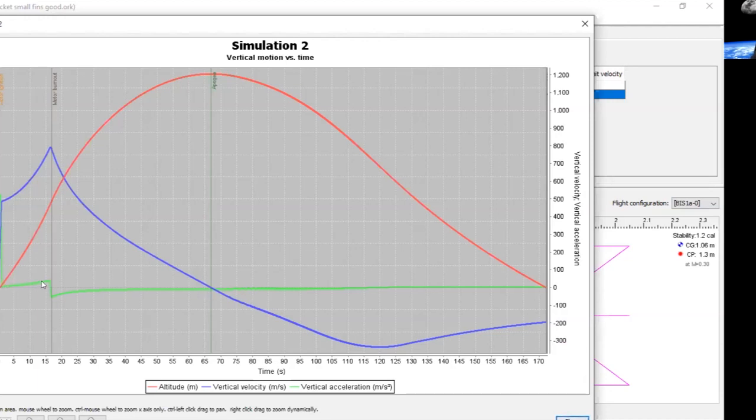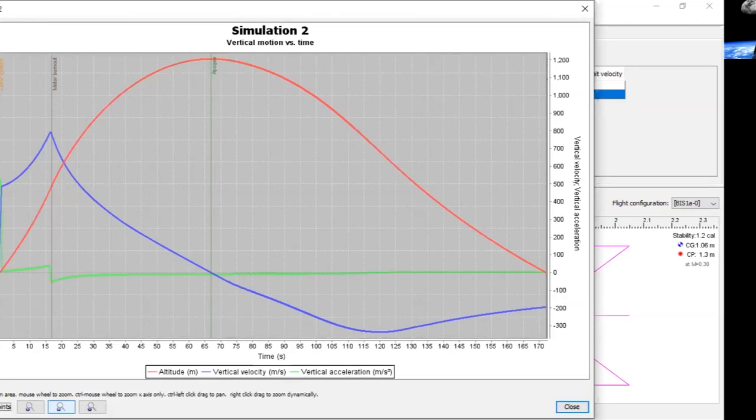This little bit here, I can just zoom in on that. The acceleration increases even though the thrust is constant, because the motor mass is dropping. As we're burning propellant, the mass of the vehicle is decreasing, the thrust is the same, and F equals ma, so acceleration is increasing. So we would expect acceleration to be increasing there. Right. So we clearly need a bigger, more powerful motor.